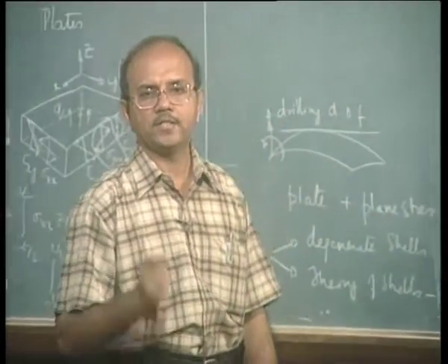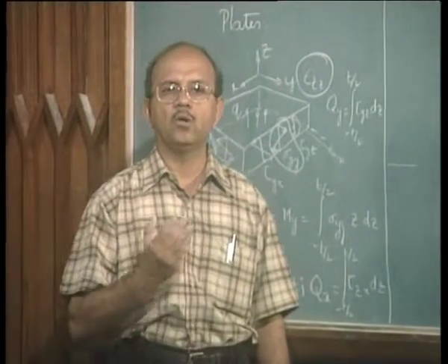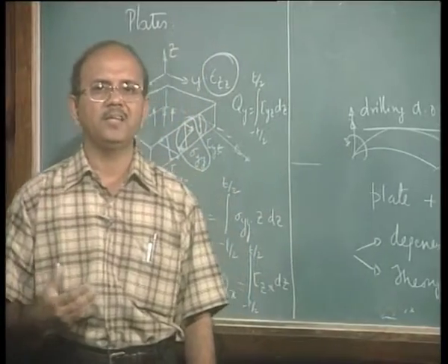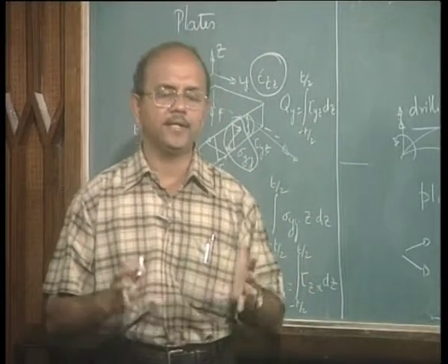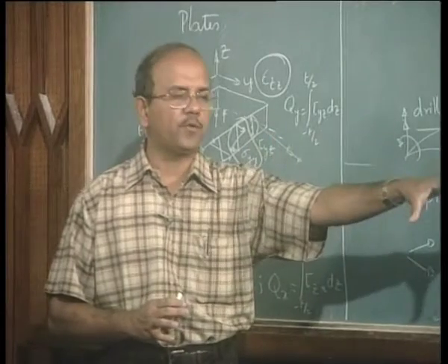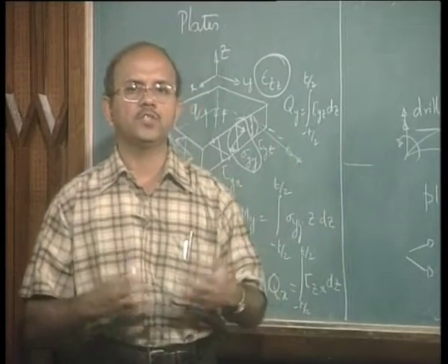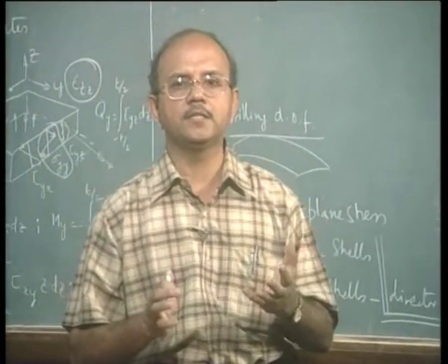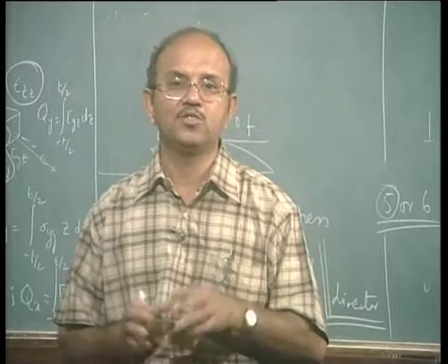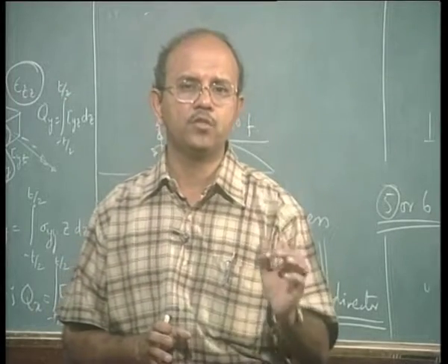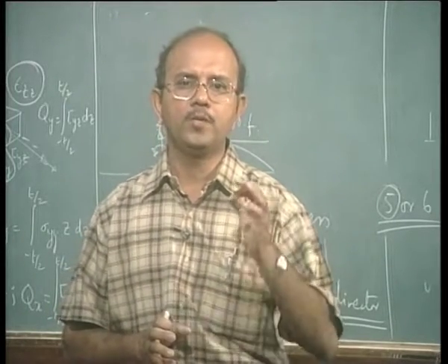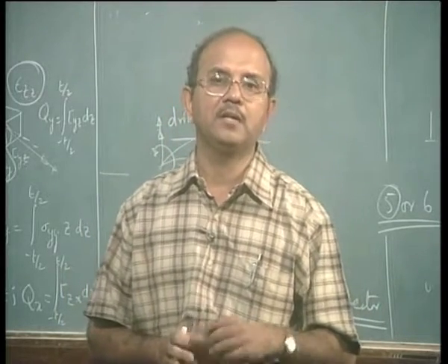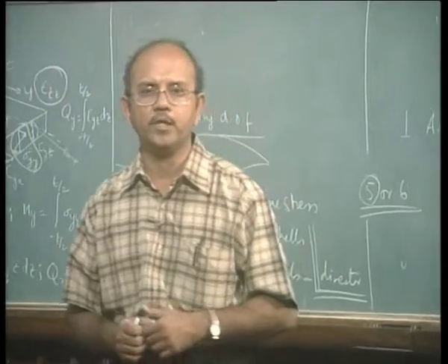We designated certain points as nodes, and if you remember, we wrote what are called interpolation functions, and we brought down the infinite degrees of freedom into finite degrees of freedom. Then using these fundamentals, we developed the stiffness matrix, and the stiffness matrix formed the basis for us to proceed further to have a relationship between force and displacement. We determined the displacement after assembling the stiffness matrix, and of course after putting down the boundary conditions.